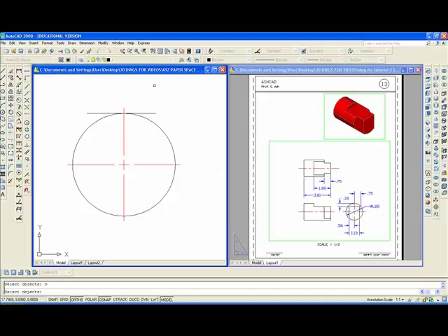Then we're going to O enter, offset, select the object, enter. Oh, that's wrong. We're going to just type O enter, give a distance of 0.38, enter, move that down there. And we're going to extend EX enter to the circle, that end, and that end. Then we're going to O again, offset, and this time 0.56, enter. We'll offset on that side and on that side, and we'll extend EX enter to this chord, both these lines.